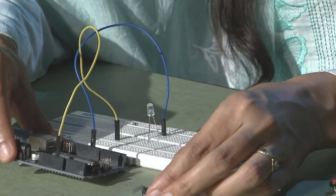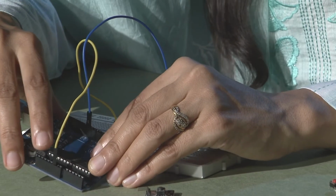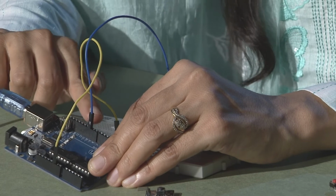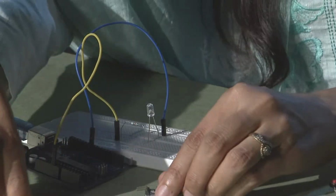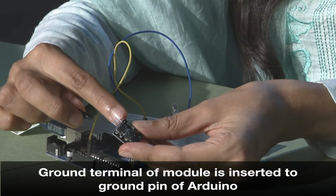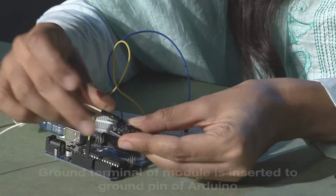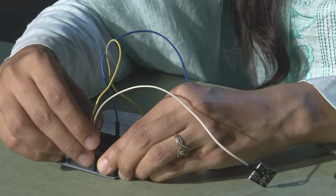Similarly, we need a 5-volt connection, which we can extend from this power terminal right now, because 5 volt is currently unused here since we have shifted our LED connection to pin number 10. So let me pick up these wires. First of all, we need to pick this negative terminal, which is the ground. I am picking up this one, and we can insert it into the ground terminal on the other end.